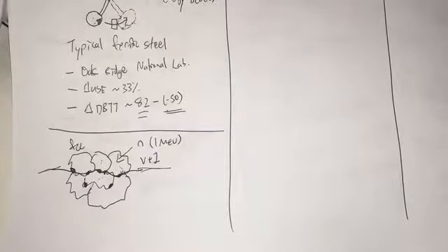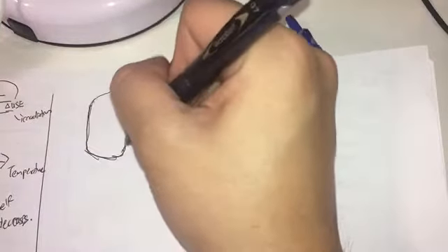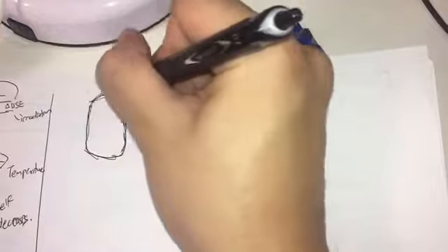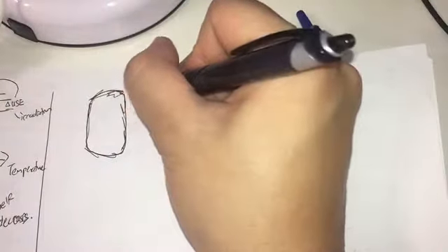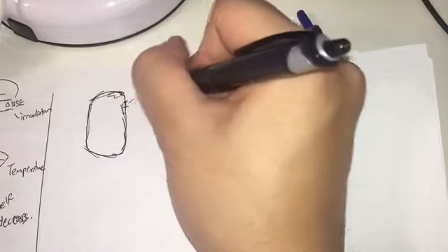During a reactor's lifetime, how do you measure this behavior? If you have a reactor pressure vessel like this, how are you going to measure this ductile to brittle transition? Are you going to chip off a piece of the reactor every year and do your Charpy test?